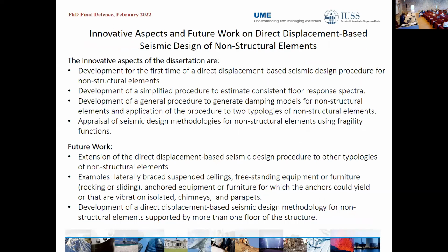The innovative aspects of the dissertation were the development, for the first time, of a direct displacement-based seismic design procedure for non-structural elements, the development of a simplified procedure to estimate consistent floor response spectra, the development of a general procedure to generate damping models for non-structural elements, and the application of this procedure to 2 typologies of non-structural elements, the appraisal of seismic design, and finally the appraisal of seismic design methodologies for non-structural elements using fragility functions.